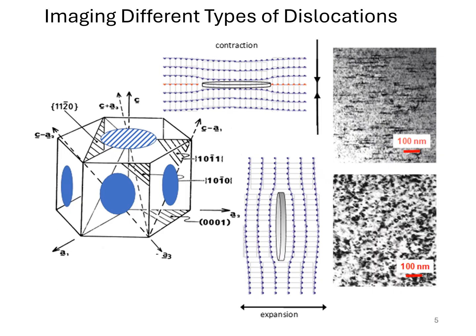Conversely, interstitials tend to form on prism planes, so that's the displaced atoms themselves, and this gives you an expansion perpendicular to the prism planes. It's a little bit more complicated than that, because depending on the temperature, depending on the alloy, depending on a number of different variables, for the prism plane dislocation loops, accumulation of point defects on prism planes, we often get a mixture of interstitial and vacancy type defects.